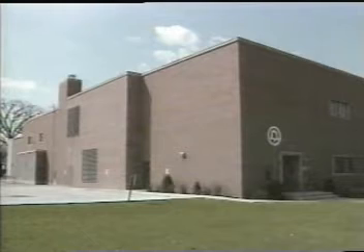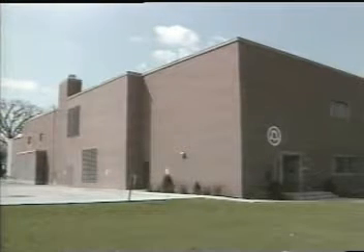Now, these cables that run through these splicing chambers and these CEVs continue back, getting larger and larger as they approach the central office. The central office is usually a fairly large building somewhere in the center of town, in strong commerce and business areas because that's where most of the demand is. The cables enter through the basement, so they come in underground out of this conduit, come up through some cable vaults, as they're referred to, or just large enclosed rooms, up into the point where they attach to the equipment in the central office, which we refer to as the main frame or the interface frame. So this is how this equipment is attached.